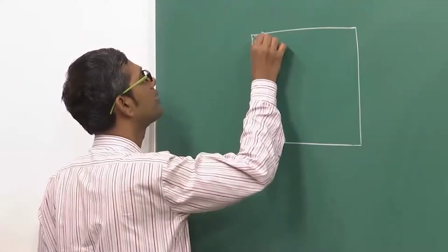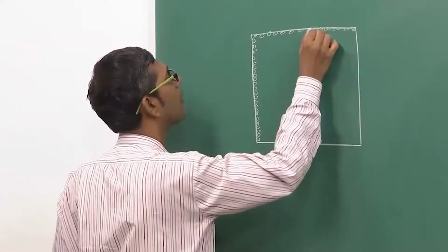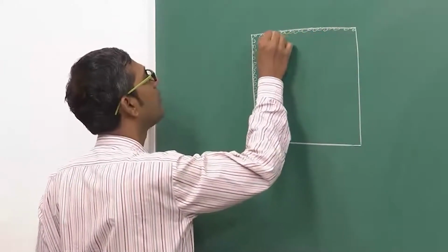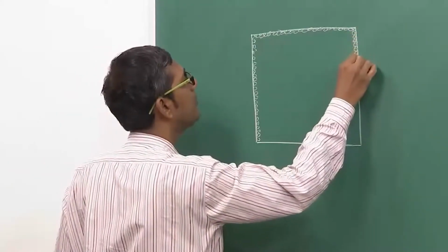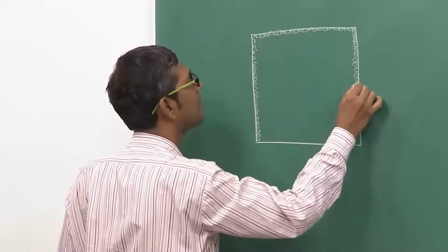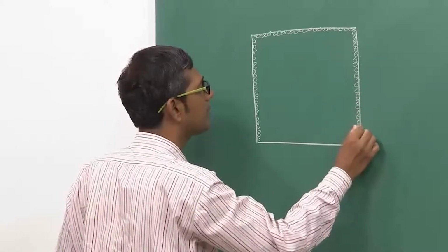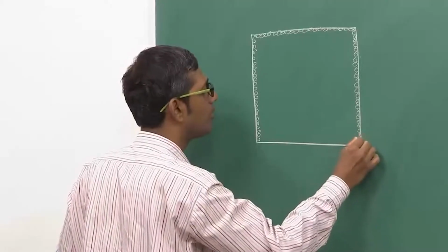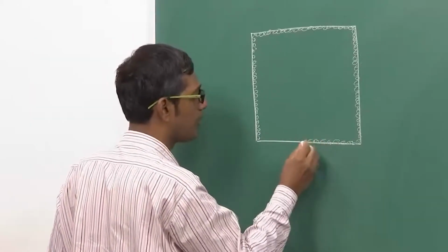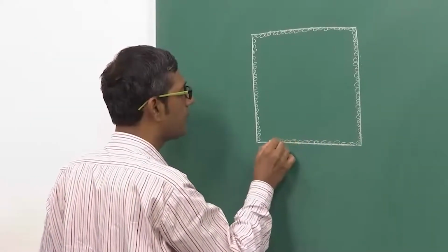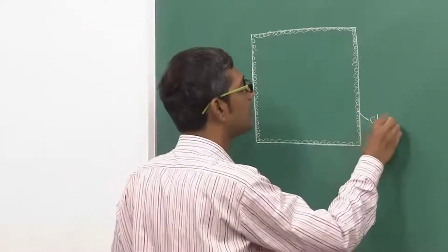Therefore, these crystals will easily form and they will be of very small size because of the large undercooling and also the cooling rate, because the liquid which is at a very high temperature will be chilled as it reaches the walls of the container. This leads to nucleation of a very large number of nuclei at the walls, and these nuclei will grow very slowly and remain very small in size because it is chilled, and this zone is known as the chilled zone in the